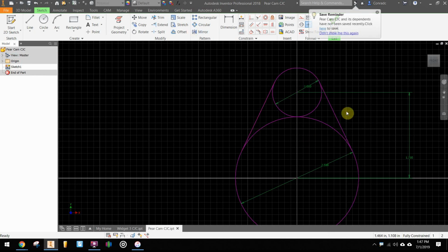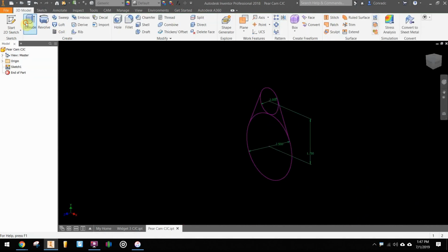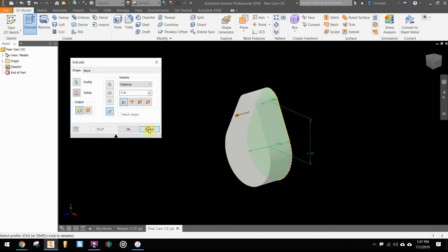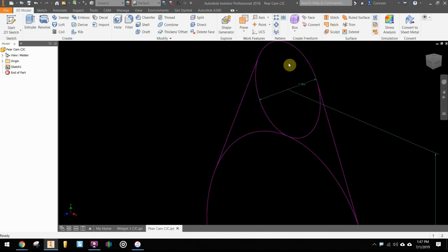Finally, this gives us a lot of intersecting profiles. So if I would try to extrude that shape, I have a lot of different profiles, and I could select different ones. But if you have one single profile, it's often best to extrude one single profile. By the way, to get back into that sketch, I don't want to create a new sketch.